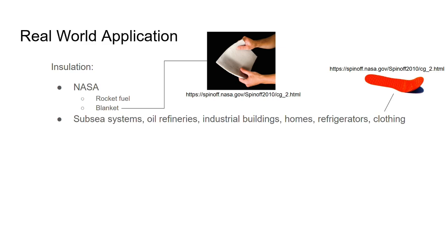Another thing that goes hand in hand with this insulative ability is its hydrophobia. This property would effectively reduce the amount of water damage on these structures or the parts inside. Now onto its surface area. One feature about having such a great surface area dispersed throughout many tiny pores is that liquid loves to hold on to it. In fact, this property is exactly what made it a gel in the first place. If you wanted, you could turn aerogel back into regular gel by letting it reabsorb the solvent used to make it originally.